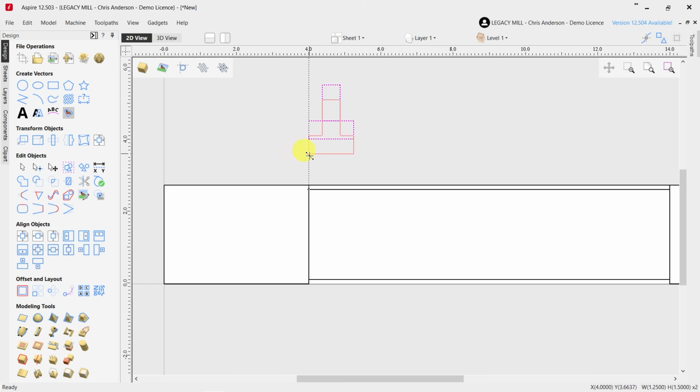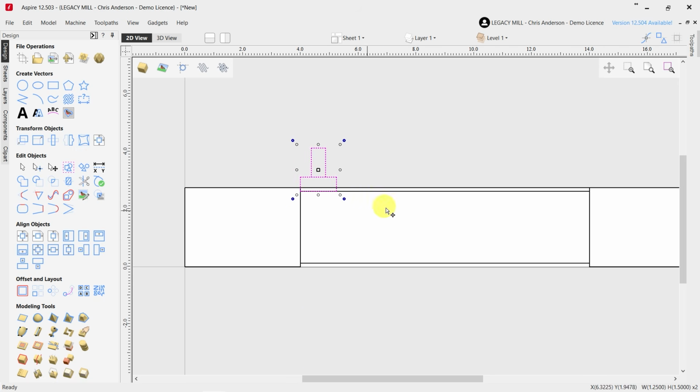And it's going to start above the material where the corners are swinging. It's not going to just plunge into the material and start cutting. It's going to approach that diameter in a controlled manner. So it's going to start out here while the stock is rotating, and it's going to plunge down until it gets to the diameter section it needs to be.